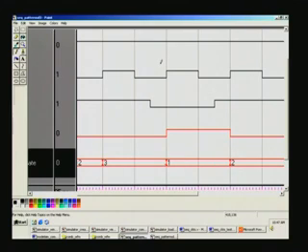Always at the positive edge of clock in state S3, you set that particular output, right, it says here. So, that means it can take place only after 1 clock delay. Are you clear? It changes from state 3 to state 1 only when the input is 0, isn't it?